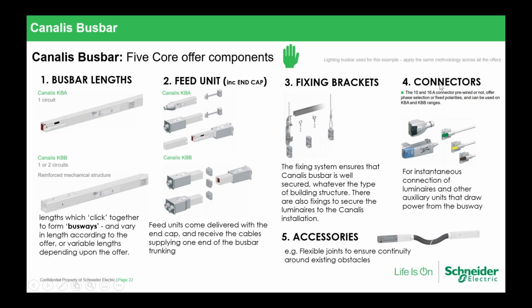The fourth component is the connectors or tap-offs. They are the ones that you connect to the busbar length in order to supply the loads. Here is an image for the lighting busbar. You have the small connectors, but on the higher ratings you have big tap-offs, not like these ones. You need to be sure you are choosing the right tap-offs.